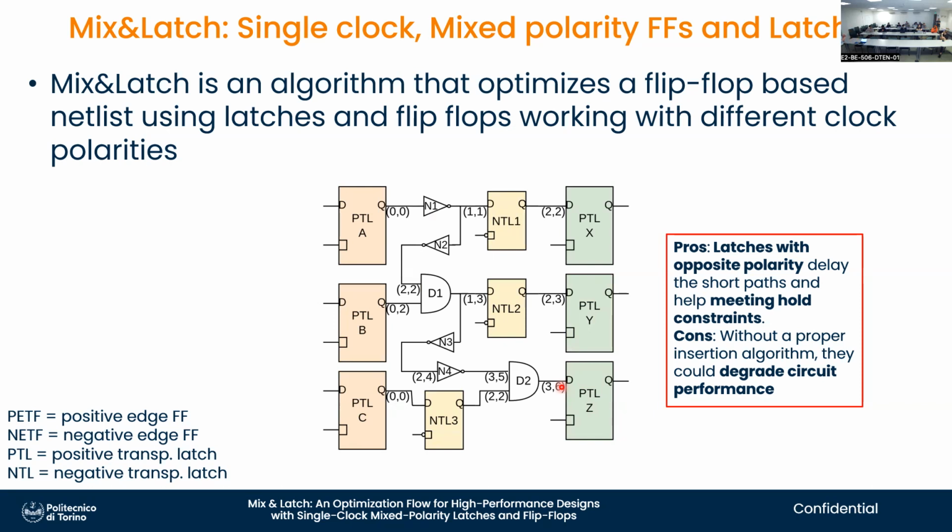Yeah, question. That thing holds if the delays are data dependent, value dependent? Here I'm using static timing analysis. All that I'm going to do is completely pattern independent. So the condition that you were saying for fixing violations, that you can find a place to insert the buffer or delays, will be data independent? Yes, this would be data independent. Yes, absolutely.